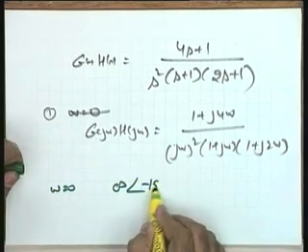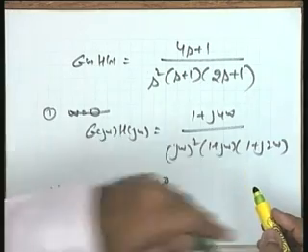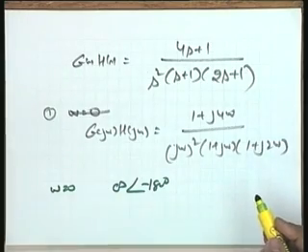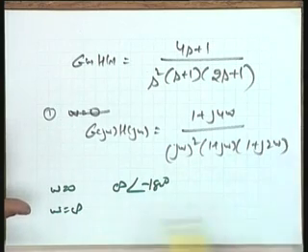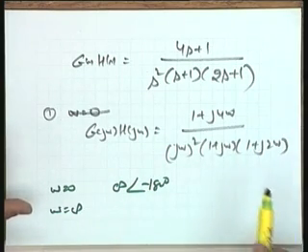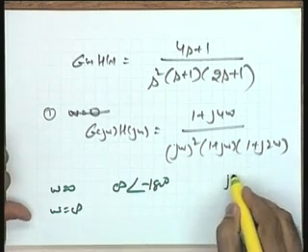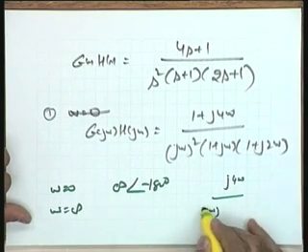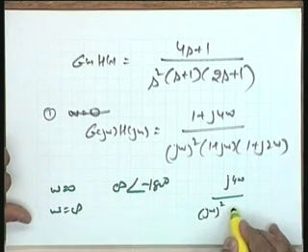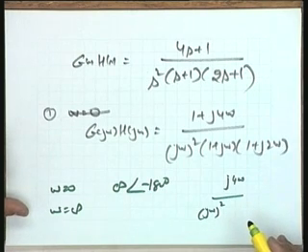Infinity at minus 180 degrees, so it is asymptotic to the minus 180 degrees line, as you find. Now if you take omega is equal to infinity, what will happen? j4 omega divided by j omega cubed gives 0 at minus 270. That is correct, please.